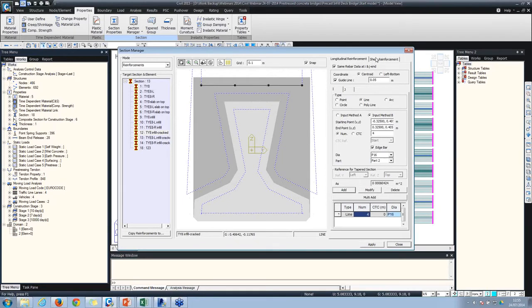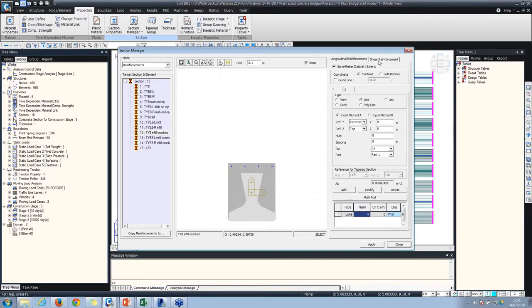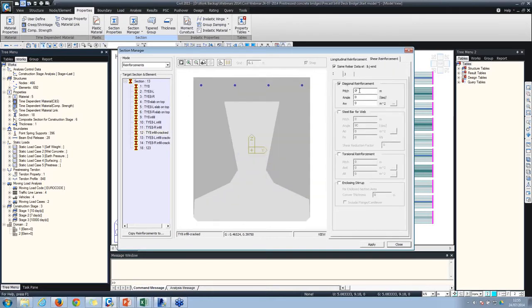You can also add shear reinforcement, which are the links for the pre-stressed concrete girder. So in the shear reinforcement option, I'll just remove the guideline. You can put in your shear reinforcement pitch, spacing of the shear reinforcement, angle with respect to horizontal longitudinal axis, and the number of legs. So 12 millimeter and number of legs, say 2, and click OK. You can also put in torsional resistance reinforcement for torsion resistance check. Again, the same way, transverse and longitudinal reinforcement which resists the torsion. You can input them here.